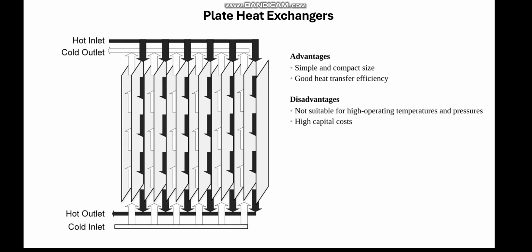However, there are some disadvantages. They are not suitable for processes with high operating temperature and pressure, and they have high capital cost. Another disadvantage is that the pumping costs are very high, because as compared to the shell and tube heat exchanger, the pressure drop in the plate heat exchanger is higher.